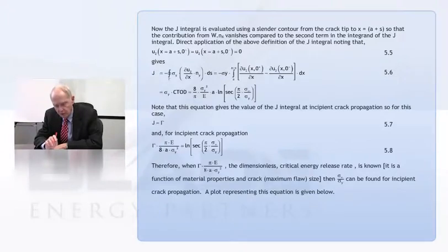The contour that we're going to take, and we're free to take any old contour we like, is a contour that includes the loading on the surface of the crack. So we're starting inside the place where we put these phony plastic stresses. We're going to go from there along the crack, right at the edge of the crack, and get to the end, and then come back, get past the plastic loading again, and stop.